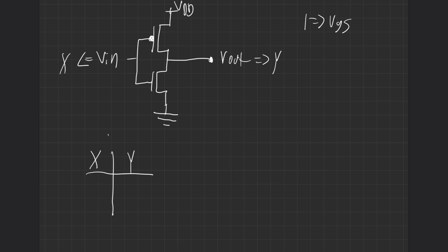if we say that X is 0, so what's that going to do? 0 is going to invert. So this is going to do the opposite. So this is going to allow current to flow, right? And then a 0 here. Okay, well, that's just going to block it, right? So clearly the current is going to come out here, right? This will be connected and this V out will be VDD, right?